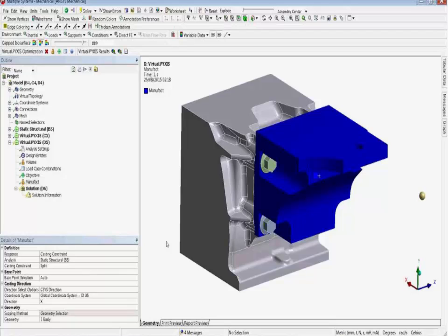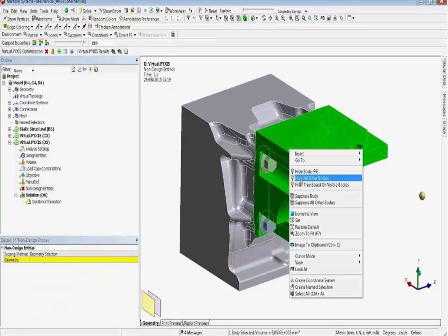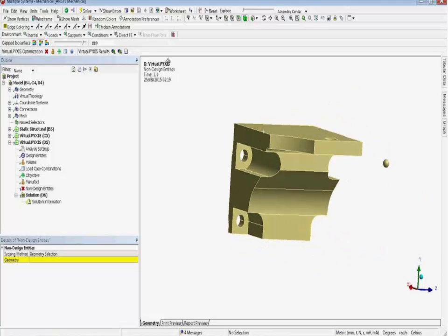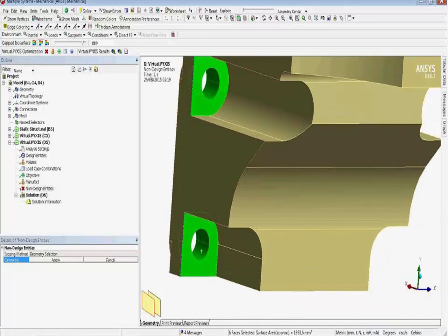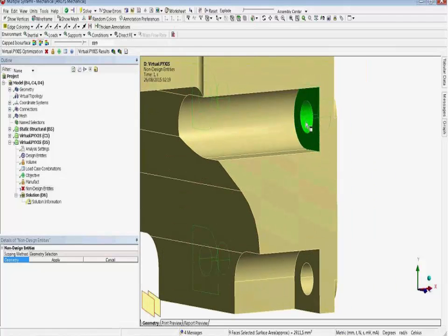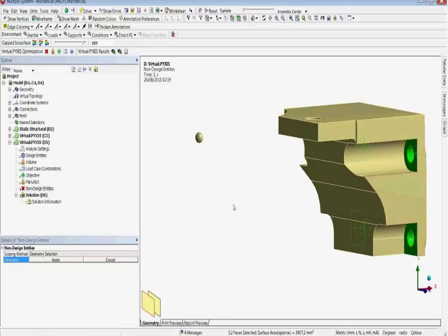One important situation, and we have run a lot of complicated models: for the same design, for example the support, you can apply different manufacturing conditions, for example different demolding directions, X or Y. And finally, I can create a situation where I tell the software some regions of my model I don't want to change, because, for example, I want to freeze these areas because they are in contact with the bolt thread.